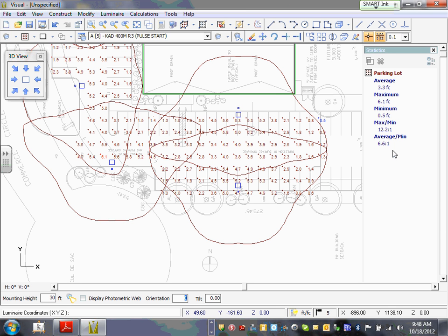Right? So how would you modify this design? Instead of using the 400 watt, guys, that big boy, what if you use 250? It gives you a smaller layout, you can get a better layout. The 400 is the cheapest design, big, it shoots all the lights and done. My calculation on the slide there is... By the way, did you guys remember that the pole height is 30? Everybody can see that it comes at a 30 foot height.